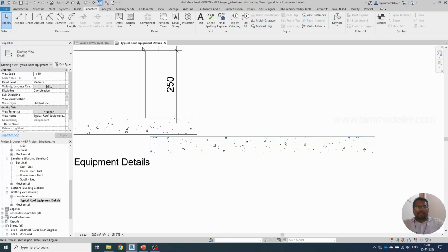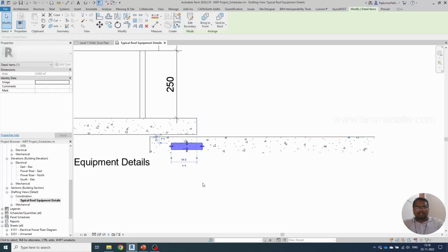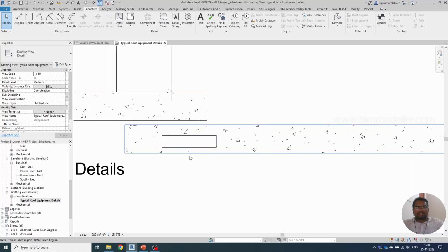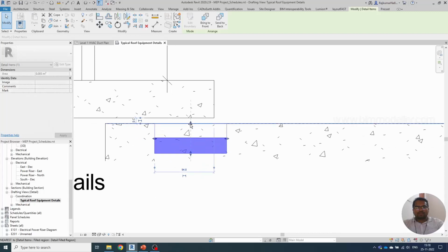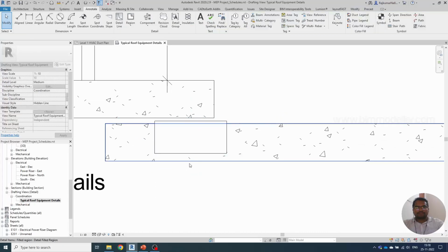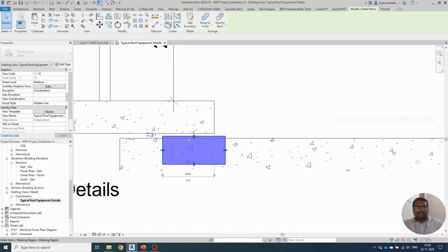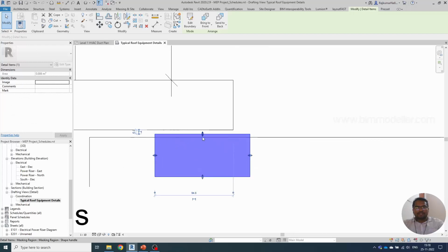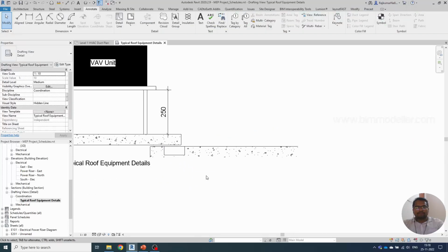While we are discussing the pattern, the masking region is nothing but something that masks the position that you need. So you can drag it like this to show a penetration or opening for the roof element like this. And if I don't want to see the dot lines on the top side, you can do it as in the previous time.